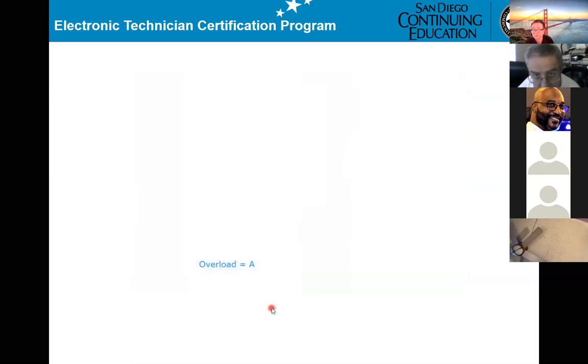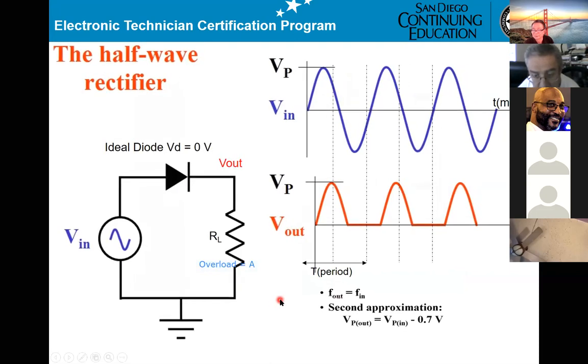Question regarding power removed from the circuit: does that also mean verifying that the capacitors are discharged? That would be a good idea. No, I don't think that's a problem. Normally, if you want to test a part on the circuit board, you better take it out.